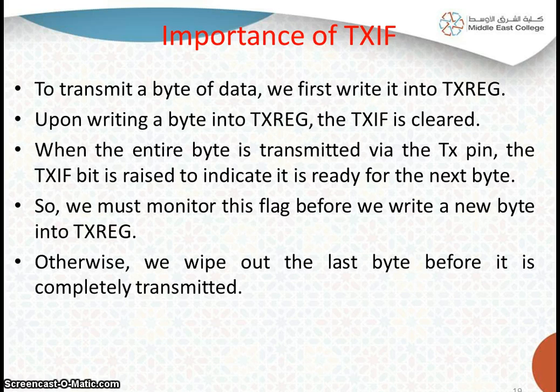It is the programmer's responsibility to check the TXIF flag before transmitting a new byte. For example, if he places data in the TXREG before the previous data is completely transmitted, then some portion of the data will be lost.